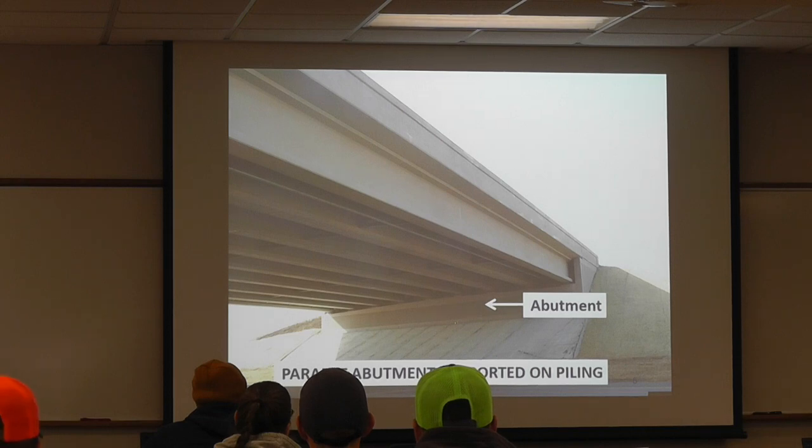So here's a parapet abutment. You can tell it's a parapet. There's no integral end diaphragm in there encapsulating the whole ends of the beams. This one, most likely, the footing is up in the fill there somewhere.